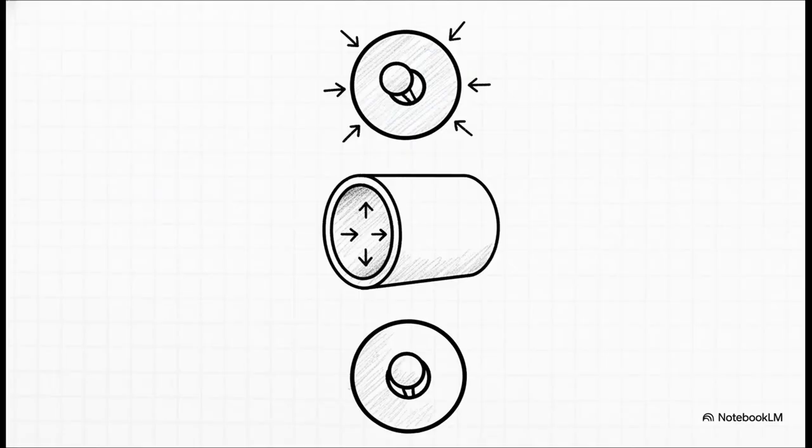Now, tucked right next to your tolerance values or datums, you might spot a little circled M or L. These are your material condition modifiers. We'll do a deep dive on these in a later lesson, but for now, just know they define how a feature's size interacts with its geometric tolerance.